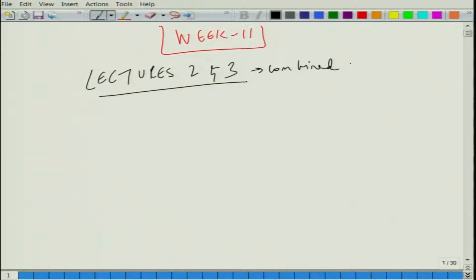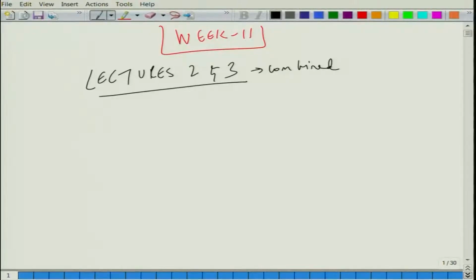So, what we are going to do exactly in this lecture is that we will present a proper theoretical formulation of how to characterize different single inlet and single outlet rectangular chamber mufflers as well as circular cylindrical mufflers with arbitrary location of ports. Although this formulation, like I mentioned in the last class, can be used to analyze systems with multiple ports, I mean more than 2 ports, like single inlet and double outlet or single inlet and triple outlet or 2 inlets and 1 outlet and different combinations, but we will restrict our discussion to single inlet and single outlet system or SISO system. So, we essentially have a 2 port system, 2 port rectangular chamber or a circular cylindrical chamber.